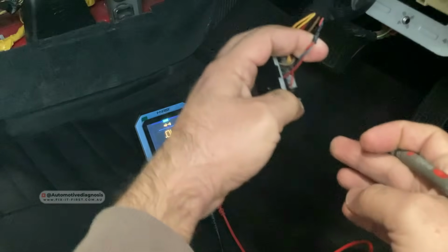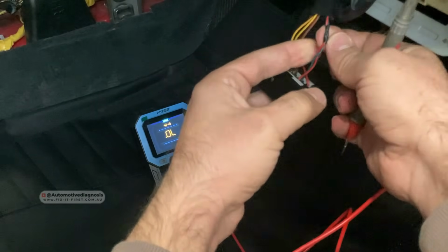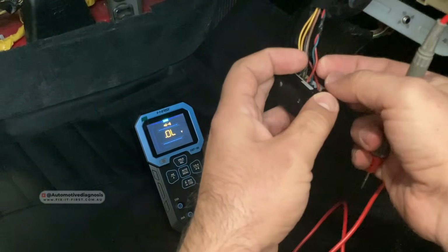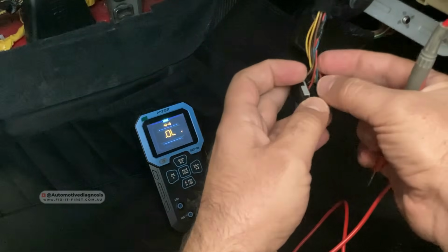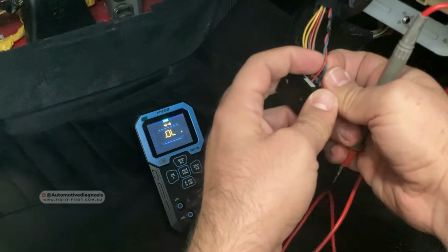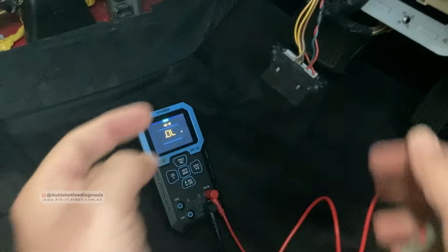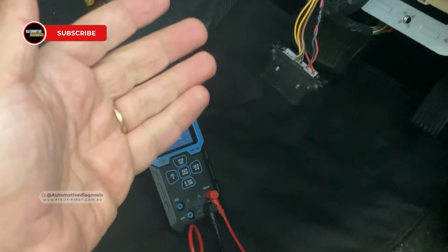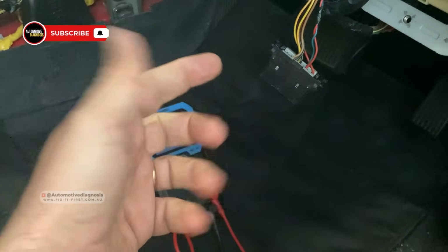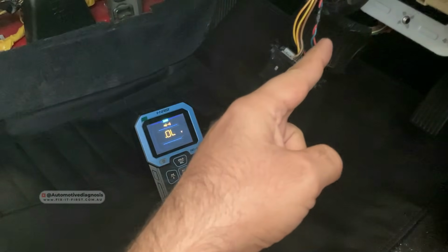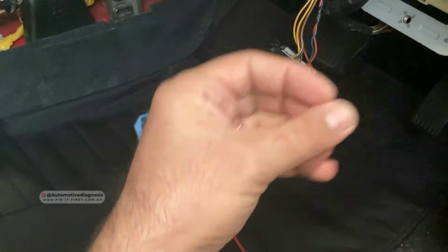So these two wires which are twisted at the back, you see that, they are for the network. The red one is CAN high, the blue one is CAN low. Of course, the color code can be different on different cars, because right now that we have CAN bus off, the problem could be short to ground on each one of these wires or short to each other.